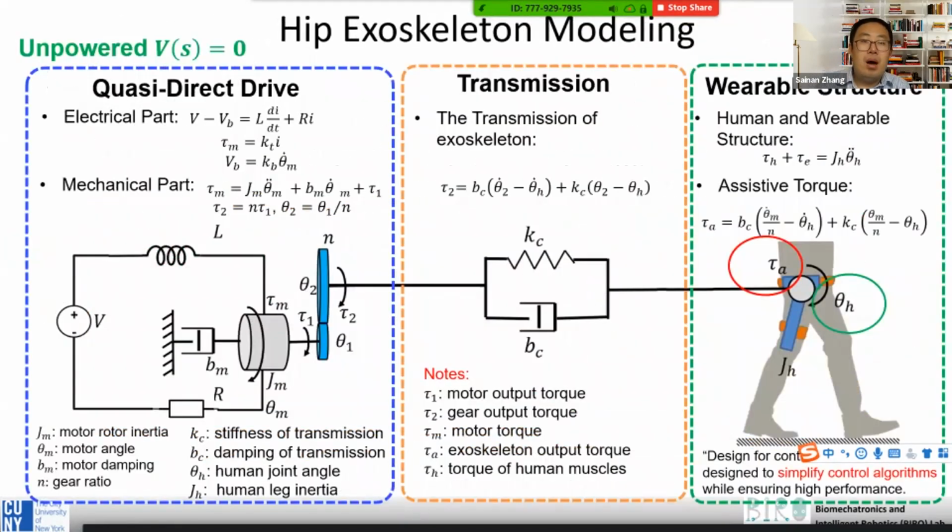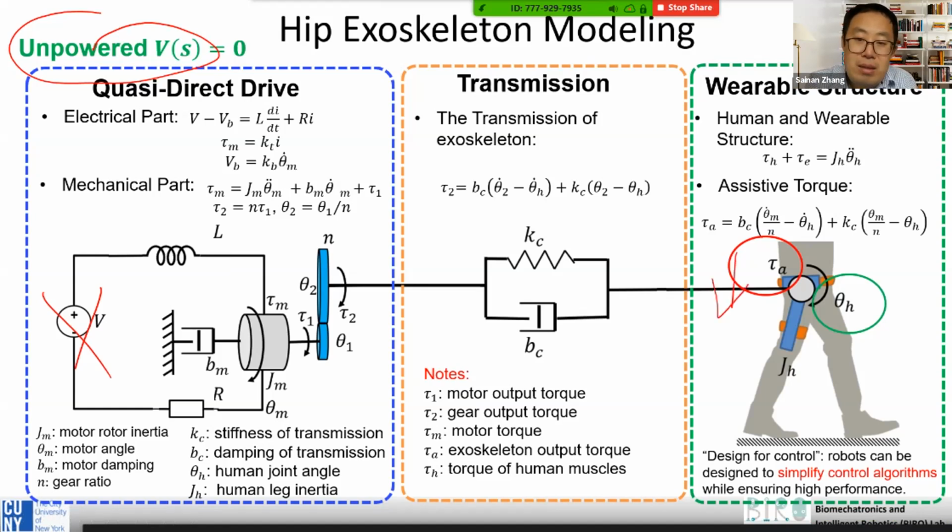The next portion is backdrivability. I mentioned that we want to do the backdrivability testing in the unpowered condition, right? In the unpowered condition, the system is not connected to the power supply. Think about the video, where we use the hammer to hit the transmission. No matter whether it's the hammer or the person, you move back and forth to drive this mechanical system, so that's why it's called backdrive. A human drives this transmission.